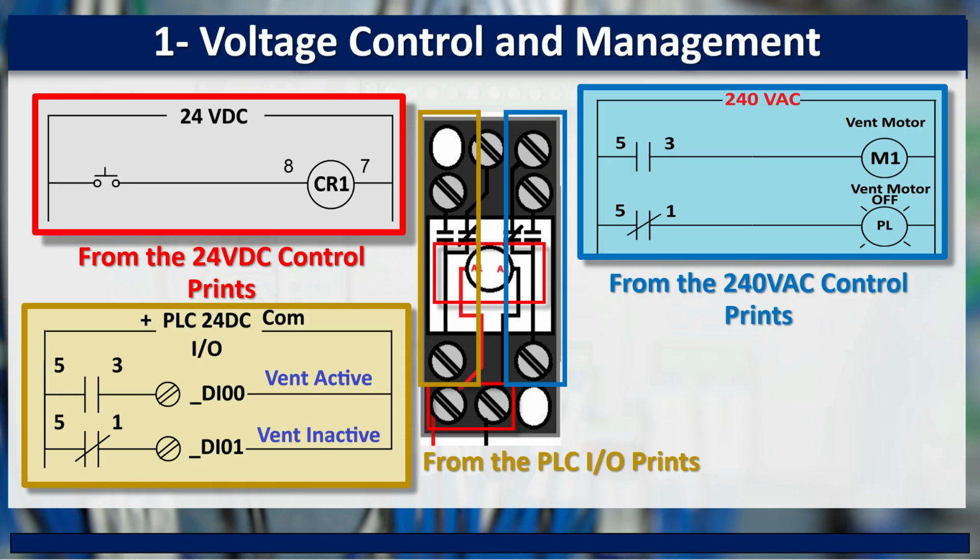This example demonstrates the principle, but the exact wiring must match the PLC input type, its sourcing or sinking arrangement, the approved design, and applicable electrical requirements. In practice, not every installation will permit or need this arrangement. The key point is that one relay can use isolated contacts to coordinate more than one voltage system and report an operation to the PLC.